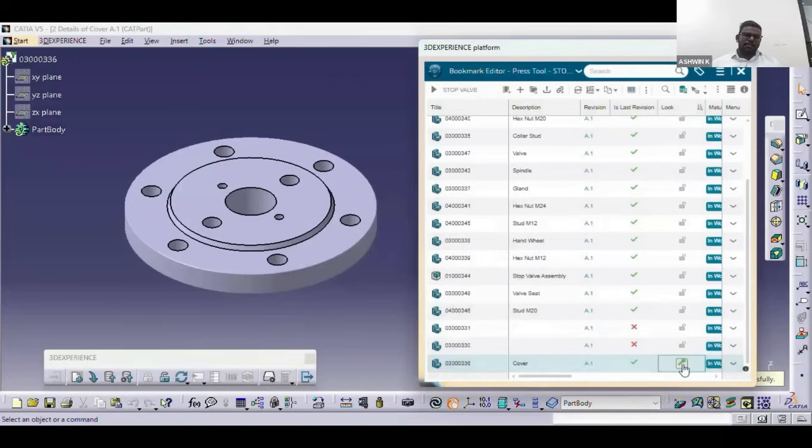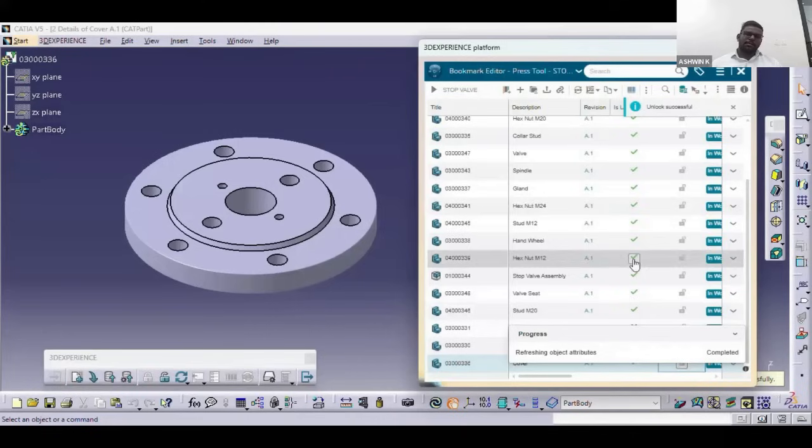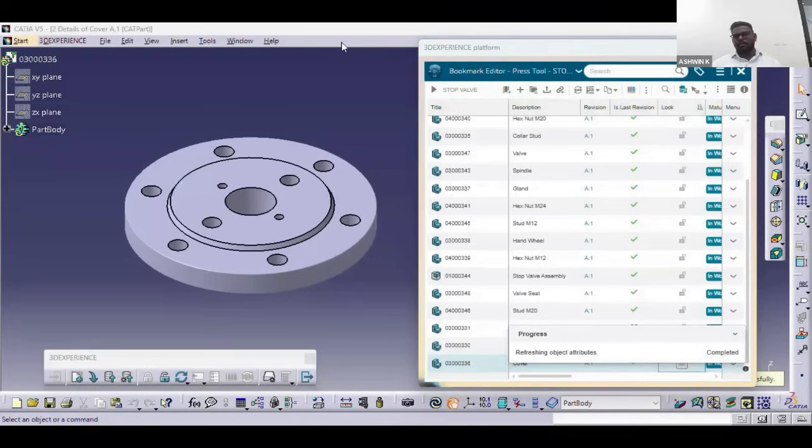So this is how we are able to connect directly from native or desktop CAD applications to the 3D Experience platform. I have showcased from CATIA, but we can connect from any other CAD application, SolidWorks, Inventor, Creo, NX CAD, right? So once that is connected, then again we can access the platform directly on the CATIA interface or CAD interface, and then we can do the saving, or properly, structurally store the data in a folder structure. Then as I mentioned, there is a lock and unlock mechanism. This is very much necessary in terms of data management.